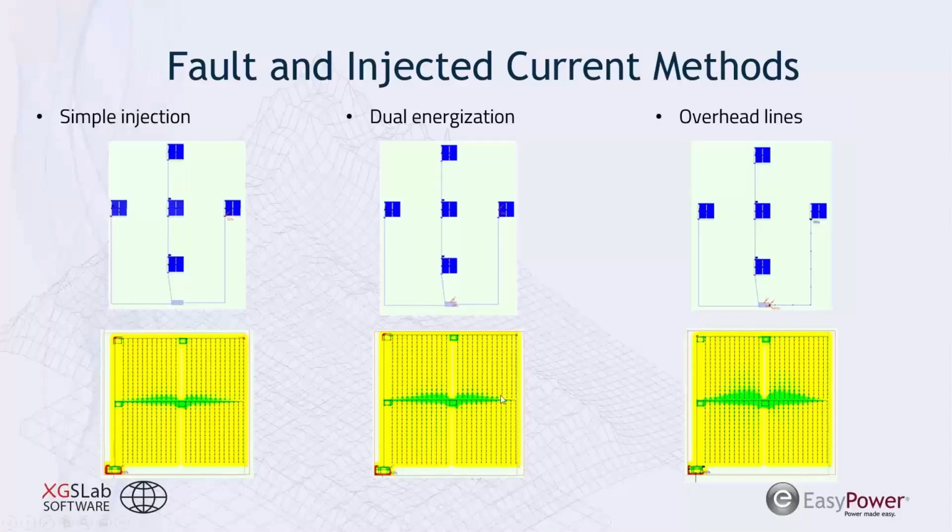And what we see is a very minor difference in the voltage values using this same green, yellow, red scale. Looks very similar. And then if we were to have this same dispersed system, but in this instance, we're actually modeling the overhead line and the neutral so that we can have the current carried out to the faulted point and then account for that mutual coupling and the conductive coupling that could occur along that distribution neutral or that collector circuit neutral. And we'll see a little bit of improvement here for this particular system.